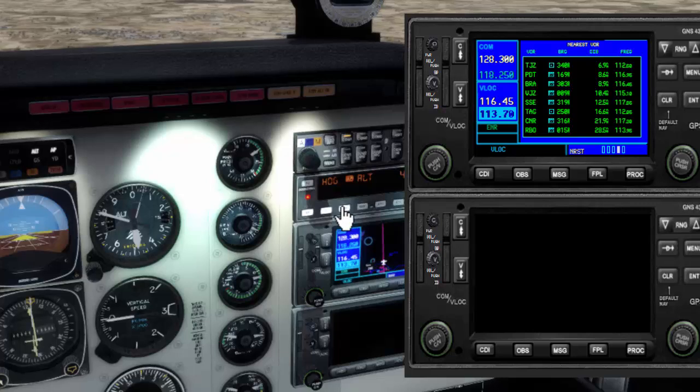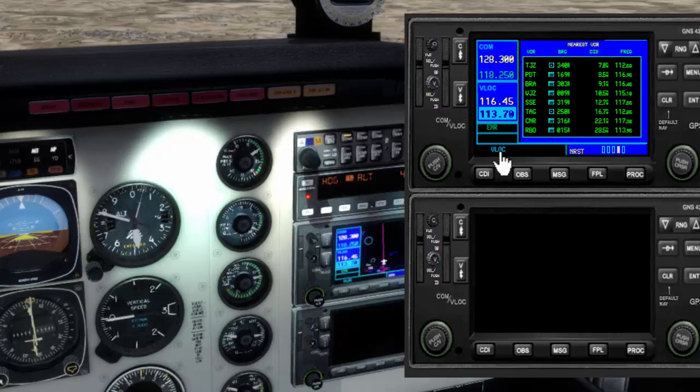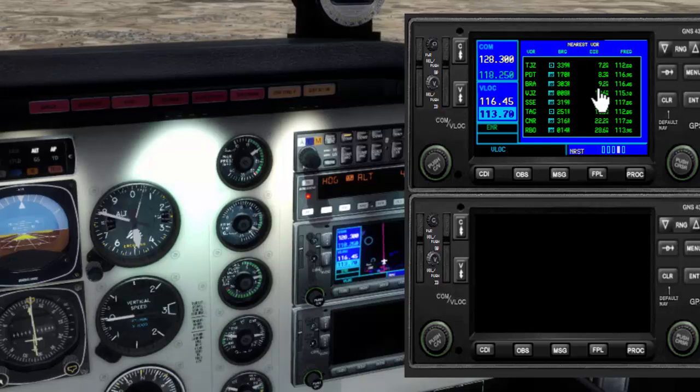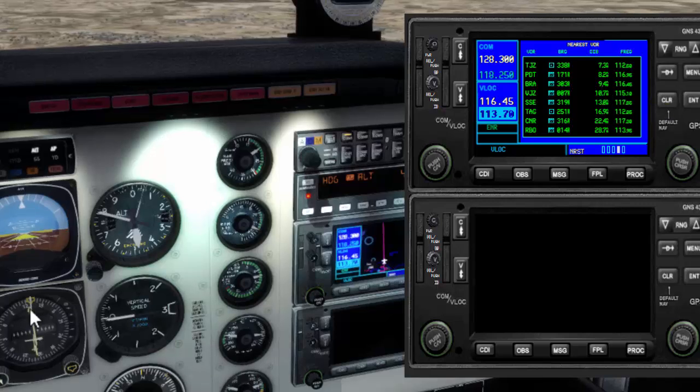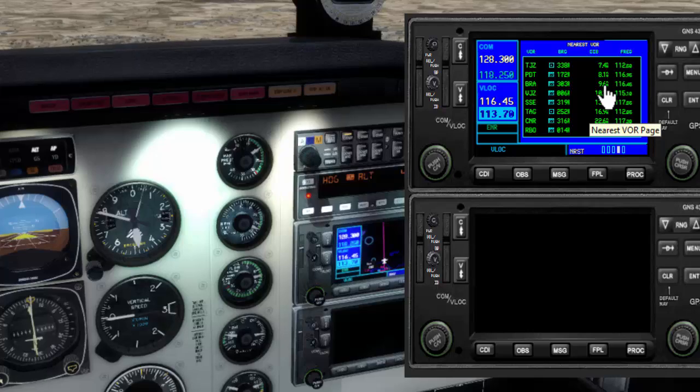So I want you to concentrate, to focus please on our takeoff and the NANDO ONE ECHO departure, and remember we are following radial 129, and we will be reaching 10 nautical miles from the Barajas VOR DME, and at that point we will be at 4,800 feet. That is what the NANDO ONE ECHO departure is telling us.